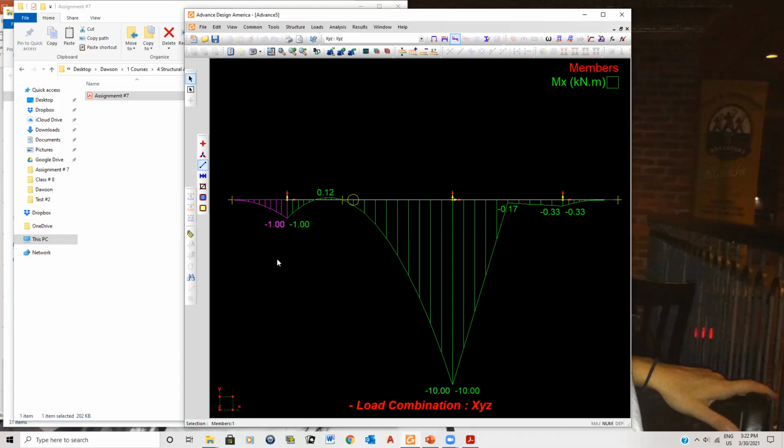So that's it, guys. I have nothing else to say. And like I said, when it comes to those moment diagrams, don't forget to add a node where the moment is so that you can apply the force. And remember, counterclockwise is a positive value for the moment, clockwise is a negative value, okay? And right now, I'm going to stop sharing. I'm going to put the record on pause.